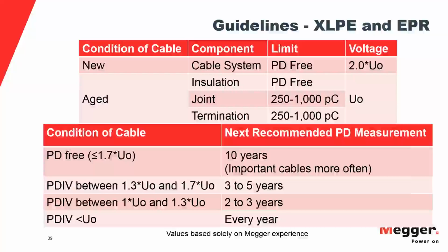So to get exactly 60 hertz frequency out of a damped AC, you need a pretty long cable, something nearer the longer lengths that this is capable of testing. As the cable gets longer, the frequency of oscillation gets slower. So when we say 500 hertz, that would be on your very short cables, something like those 200-meter cables without the support capacitor might be oscillating in the range of 500 hertz. But something a couple of kilometers long might be in the range of 60 hertz or something.